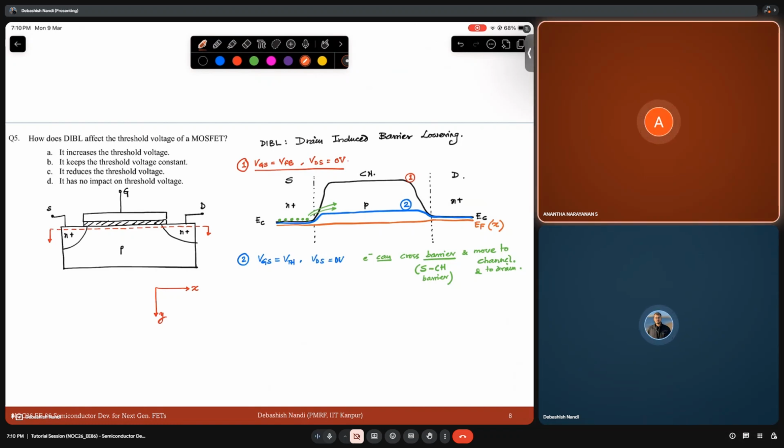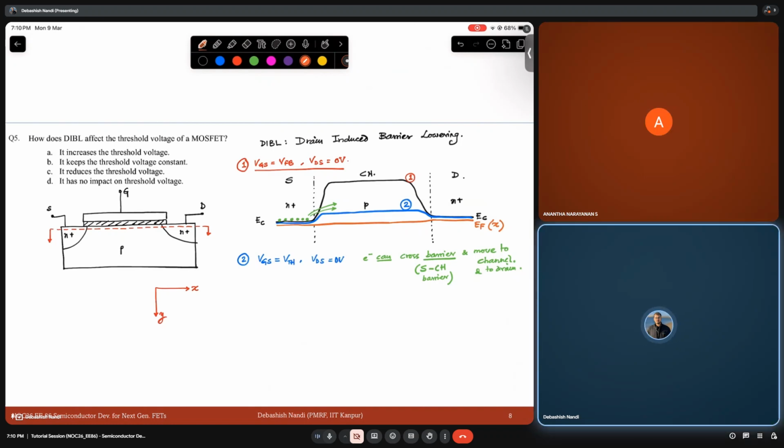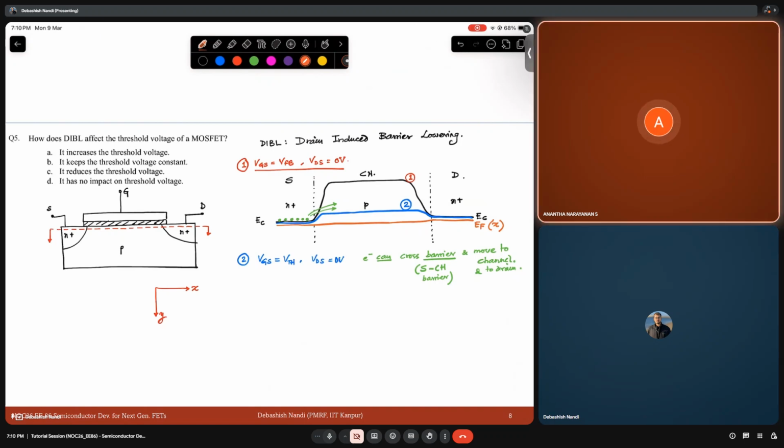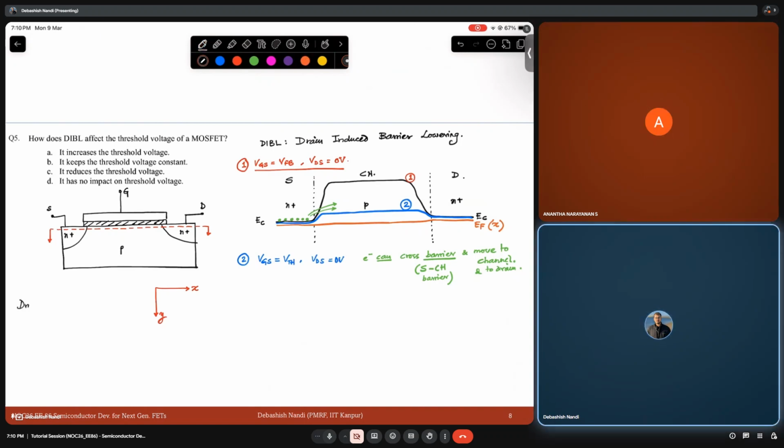But why? Because of EF, that region current will flow, right, sir? It's because of that reason current will flow, right, sir? Because Fermi level at Y will change. No. Is current flowing in the y direction or in the x direction? It will be flowing in the x direction. So what does your drift diffusion equation tell you? That must be q dp by dx, right? No, sir, no. That is not the drift diffusion equation. So drift diffusion equation, what does it tell you?